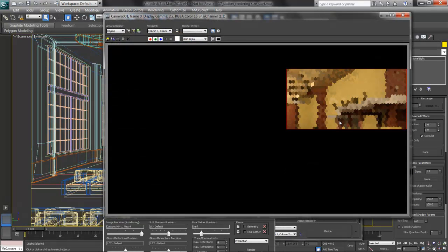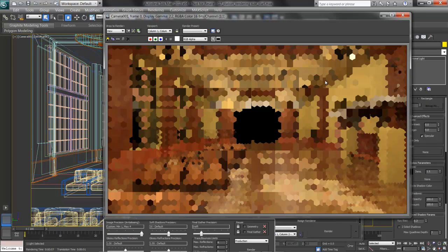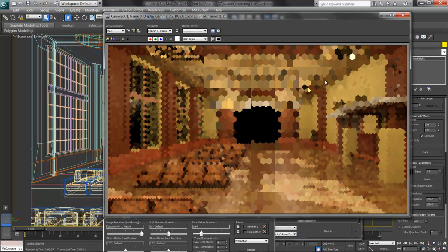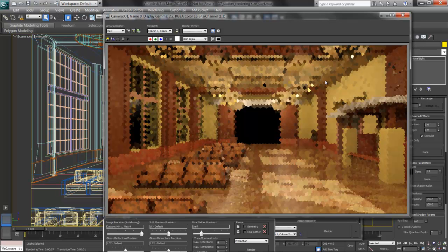It looks like I've forgotten to switch away from region. I'll hit Escape and make sure I drop down under Area to Render and choose View, and hit Render again. There goes the whole image. And in a few minutes, I'll see my whole train station rendered from that camera at 1280 by 720 with pretty good anti-aliasing. Once we've got the render size nailed down, we can look at things like anti-aliasing, the quality in our reflections and refractions if we have them, the quality of our shadows, and also the quality of our bounced light, which we'll do in the next videos.